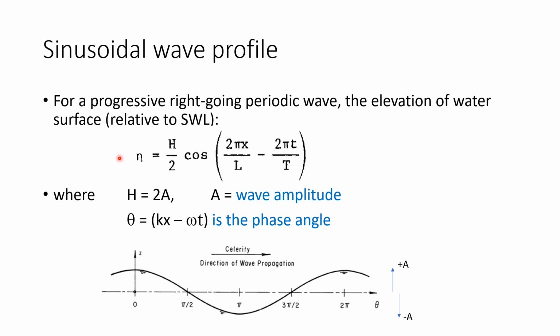So when we are looking at the wave crest, cosine equals 1, so that eta equals the wave amplitude and is positive. But when we are looking at the wave trough, the cosine function equals -1 and eta equals -a. Still the amplitude, but now negative. That means the surface of water has moved downwards. Basically, H equals 2a.